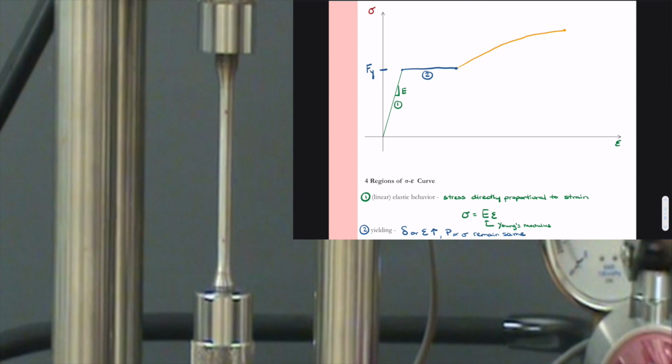From a material perspective, what's happening in a ductile metal is that all the dislocations at the atomic level are shifting to the grain boundaries, and then at the grain boundaries they tangle, and it takes additional force to break those bonds to get additional movement in the material. So that's what it means by strain hardening. These dislocations tangle. We need extra force to keep stretching the material.